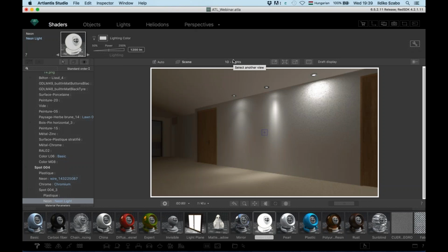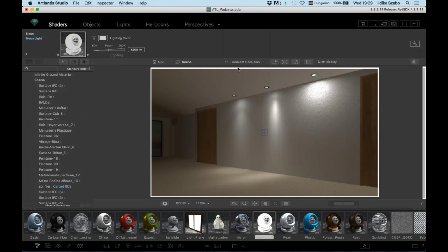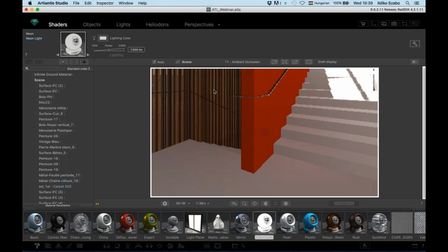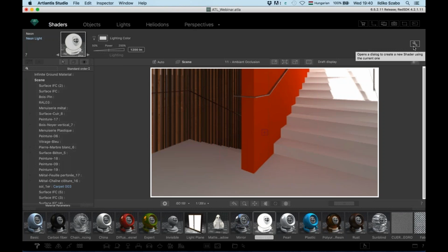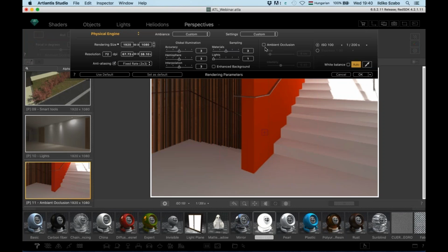So briefly about artificial lights, introducing you to artificial lights. Some other productivity tools: ambient occlusion, this virtual shadow that will enrich our scenes. And here is a situation with these stairs where the geometry is not emphasized so well. The shadows and the lit portions are not so differentiated. Therefore, I will use this virtual shadow in order to emphasize even more the steps, the stairs.